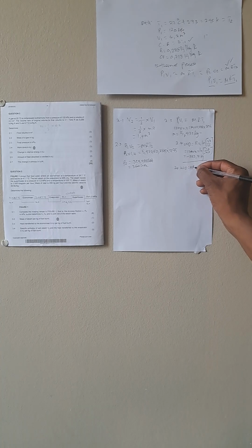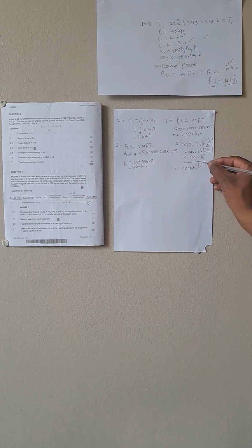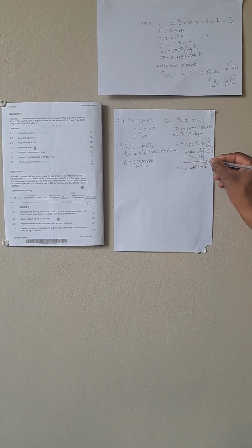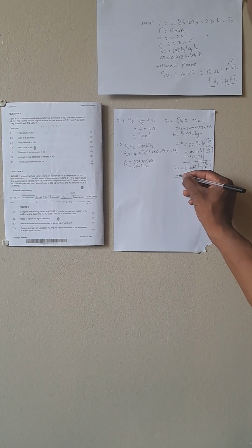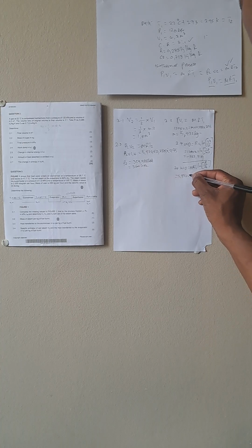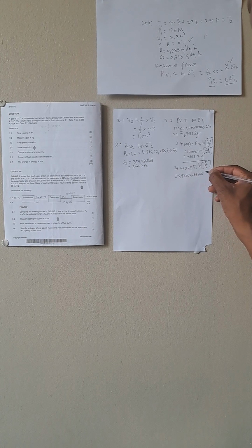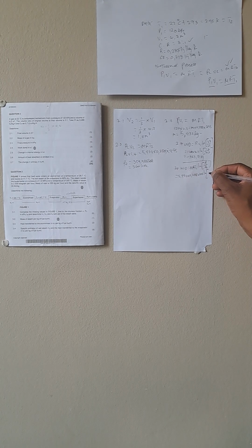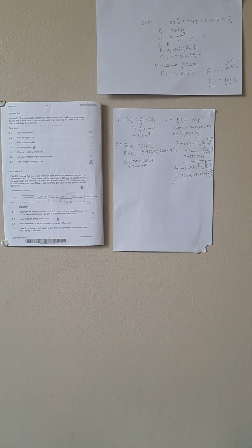So we can use here our MRT1 ln of the ratio of our pressures, P1 over P2. This formula is also there on your formula sheet. So let's substitute our mass 5.932, our gas constant 0.288, T1 295, and P2, we got 360. Our P1 was given, it's 120.